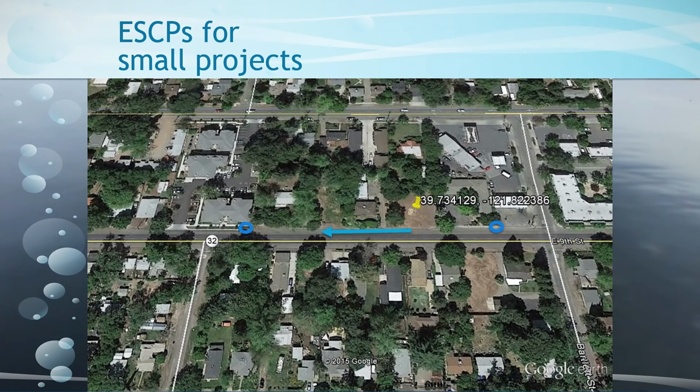First off, flow's going east to west, and both the DIs are more than 50 feet away. And the only DI we'd be really concerned with is the one down gradient, because that's the one that would probably be getting the sediment, but that's more than 50 feet away. So as far as the city's concerned, that's an option.